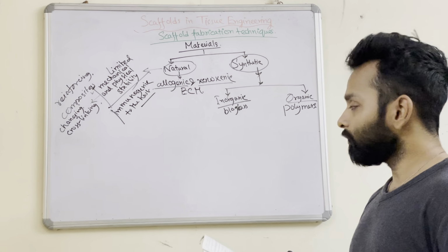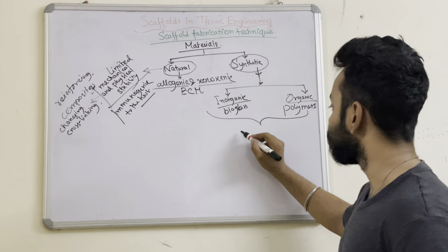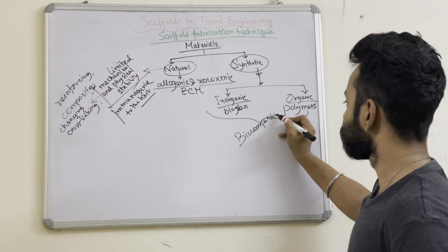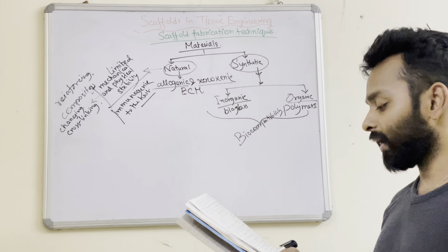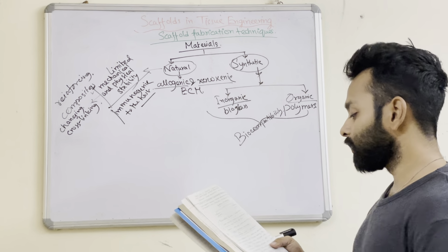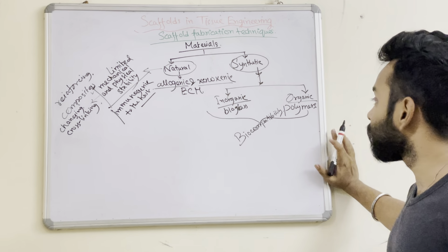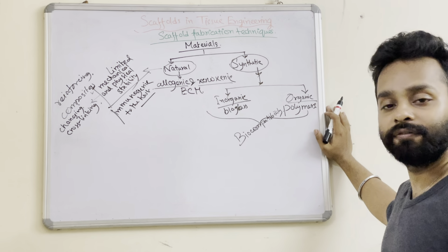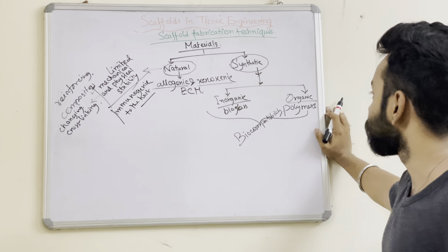The main disadvantage of the synthetic type is the biocompatibility. This can be improved by coating the materials with substances such as collagen. But with synthetic biomaterials for fabricating such scaffolds, it is possible to better control the physical and mechanical properties, which can be tailored for both hard and soft tissues.